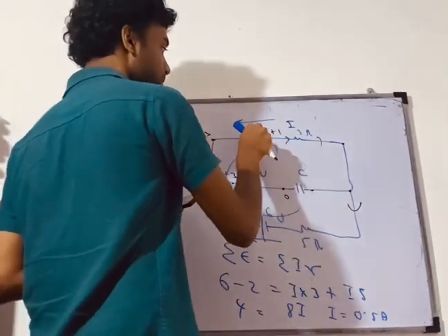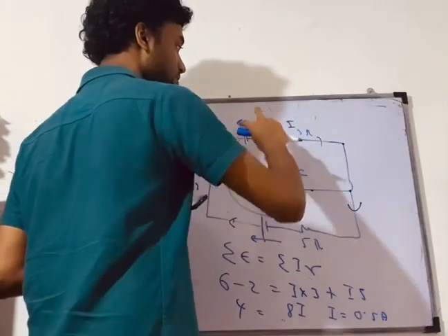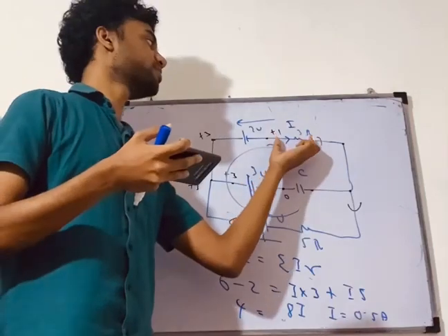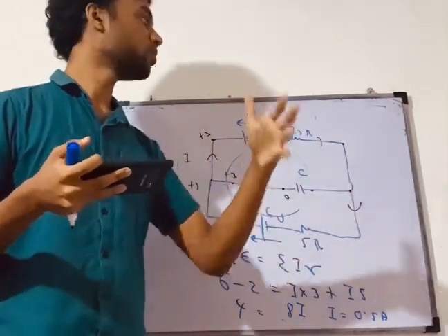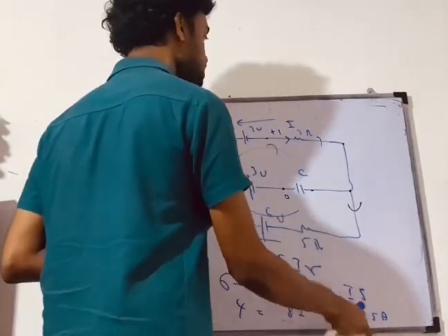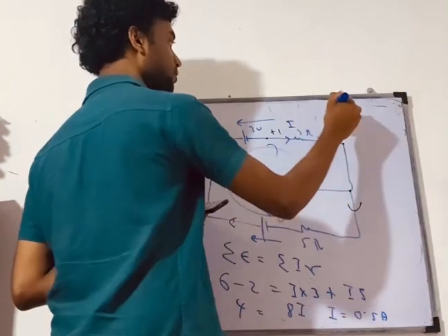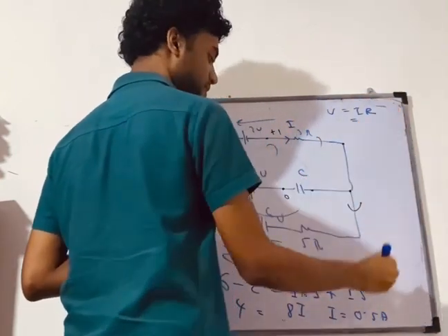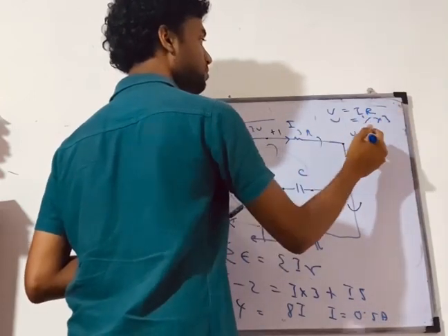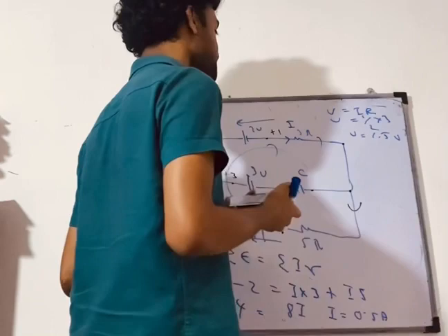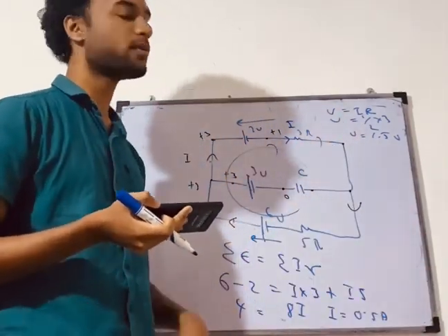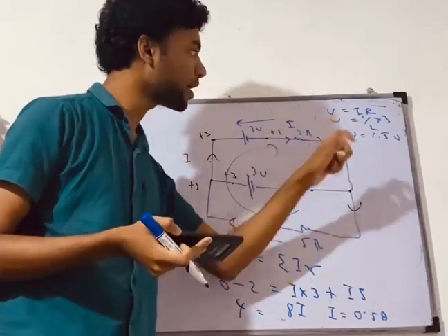If you know the current now, when current is flowing through this resistor, there's going to be a potential drop. There's a potential difference across these 3 ohms. So I had 1 here, and a current of 0.5 goes across 3 ohms. You know V equals IR. Then if the current is half, resistance is 3, I get the potential difference across the resistor to be 1.5 volts. So you know the potential drop is going to be 1.5 volts. So from 1, I should subtract 1.5 volts.